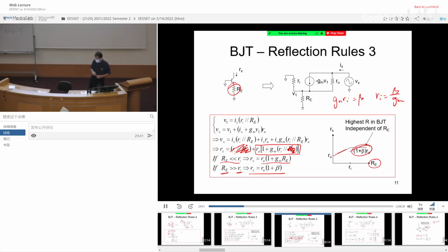I mentioned this because later we are going to visit cascode design. For MOSFET, it is very useful. Use cascode with two devices because this device has R0. I insert the R0, so looking from the top, my resistance increases further. And if this resistance is increased further, let's cascade another one.